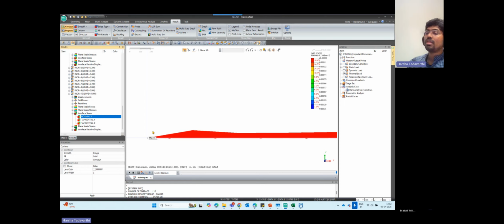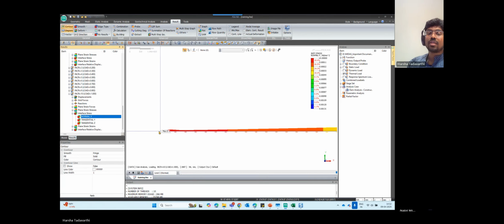That means since the normal stress becomes 0, the tension crack is going to get started. Until all the other locations are negative in nature, they are still experiencing compressive forces. Had the dam overturned completely, then everything would be represented as tension. Right now, only the heel portion has the tension, and hence the normal stress is 0 here. And at all the other locations we have compression.